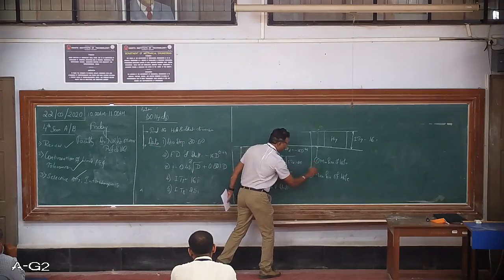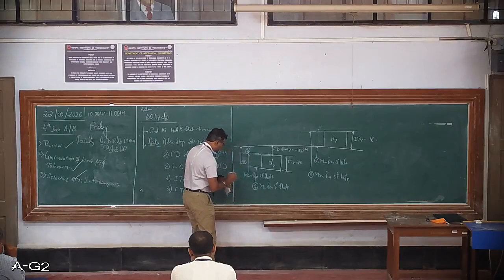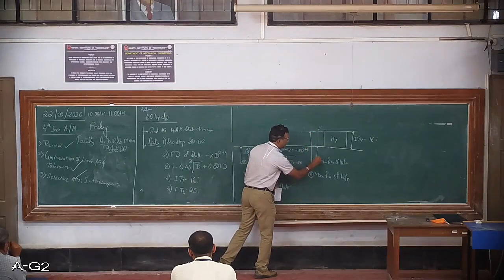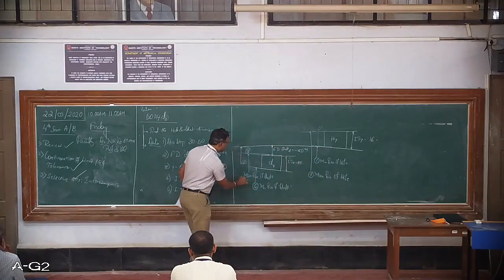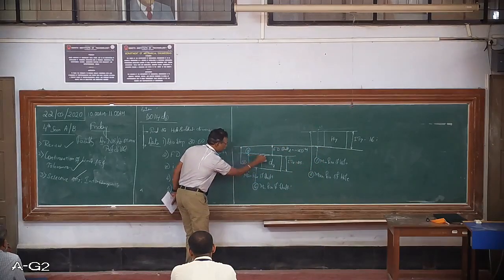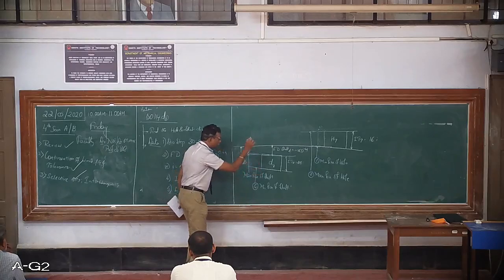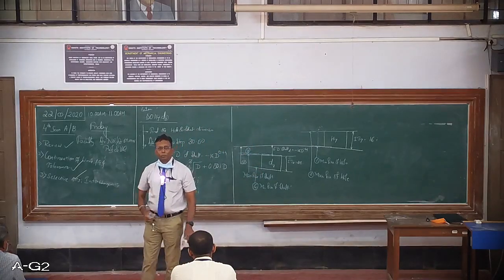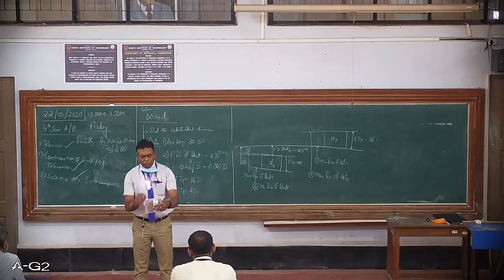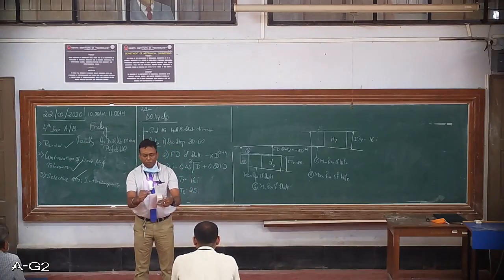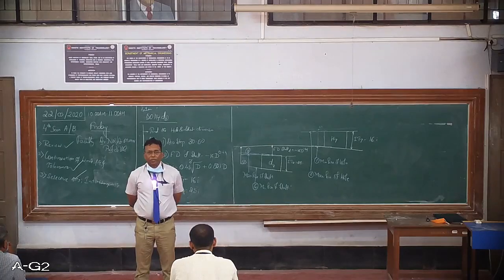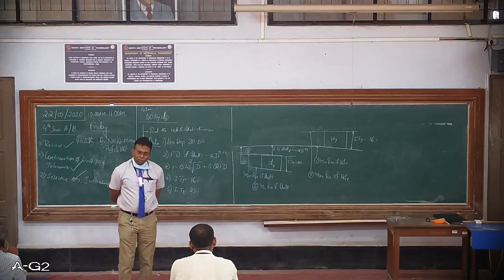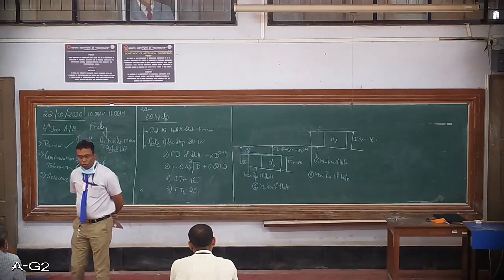So these are the four things that we need to calculate. One, maximum size of the hole. Second, minimum size of the hole. Third, maximum size of the shaft. Fourth, minimum size of the shaft. Please note students, this is only 50% of the numerical. It is given right at the beginning only for hole and shaft design. But the problem can as well be asked as design go and no-go gauges, that we will discuss in our further classes.